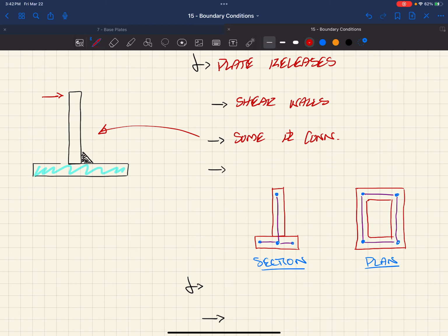If we didn't take away that stiffness, that would mean that if we provided loads to where we have demand at that location, say we model it as if there's a fillet weld here, now all of a sudden there's resistance to moment in this direction. Say we did have some loads that were out of plane to this plate. Before, if this was pinned, they'd have to travel somewhere else throughout this connection. If we fix it, now we do have demands here.